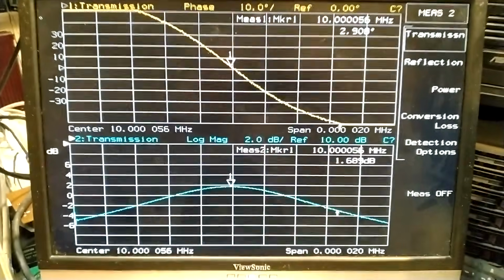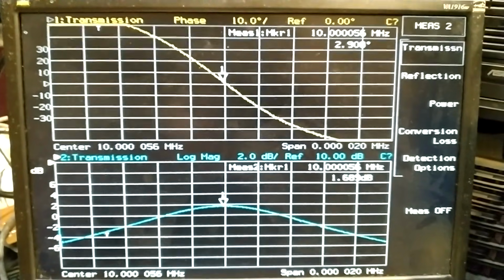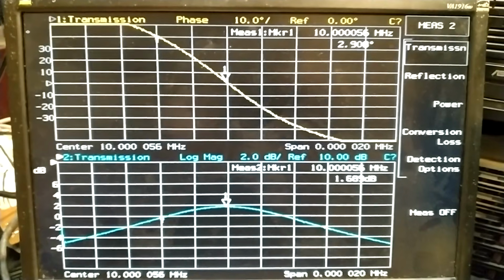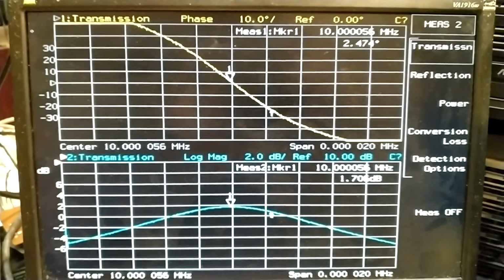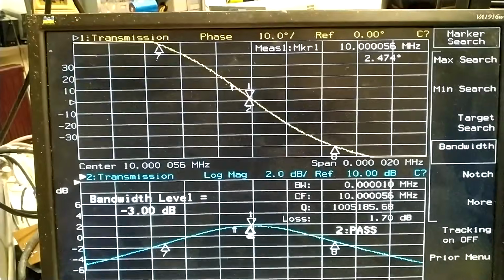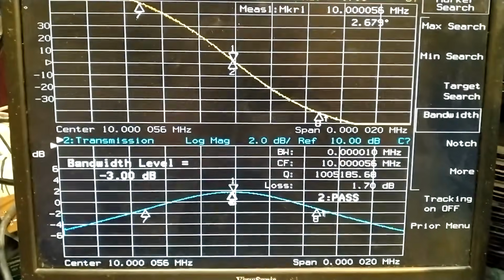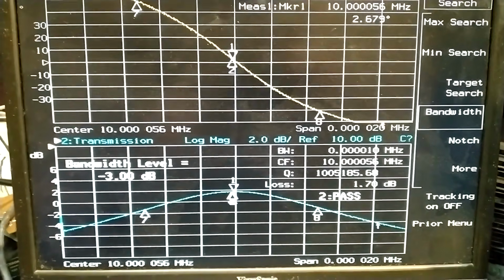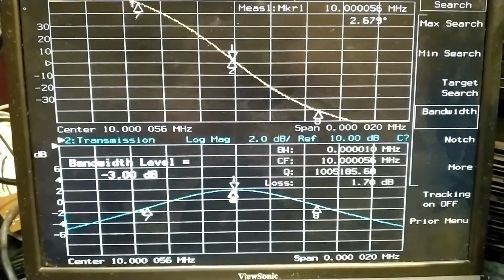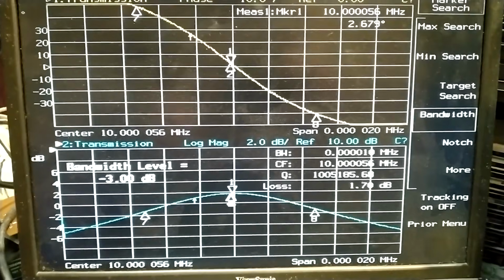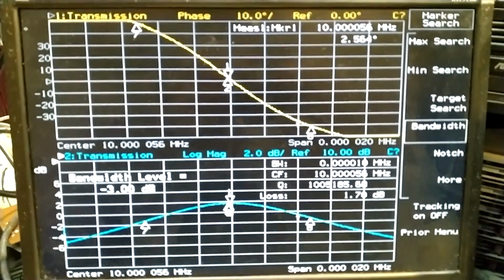Now I have gone to the other extreme. The tuning capacitor is only 22 pF. The frequency is much higher. It's about 30 Hz above the Wenzel oscillator now. Q is now about 1 million. It is a little bit lower than before, but the impedance is much higher. I have had to transform the impedance downwards to get the same level as I have had before.